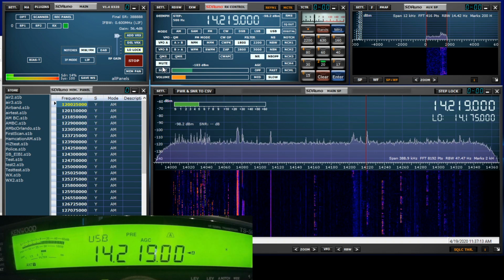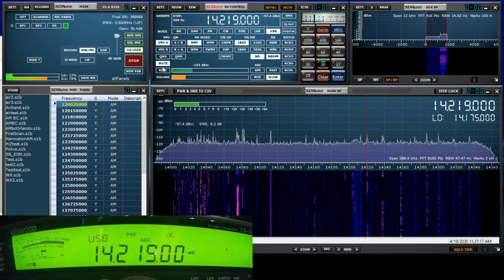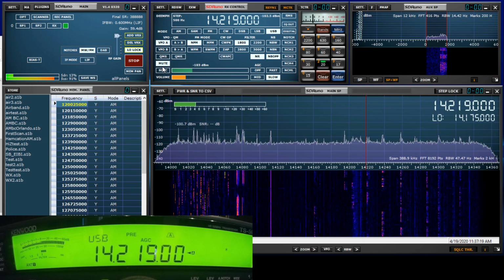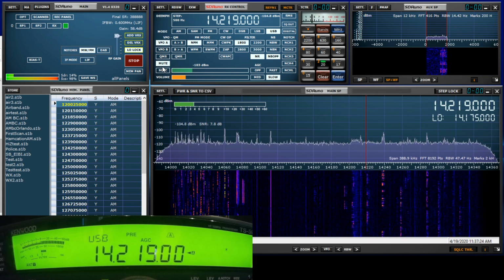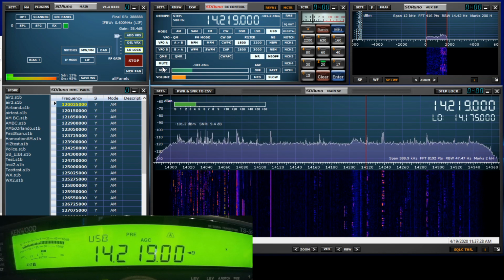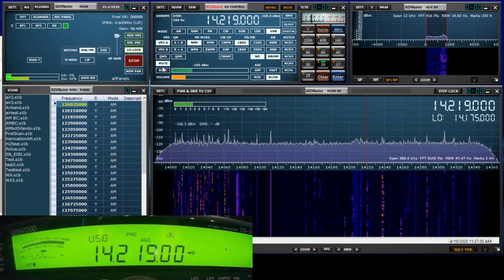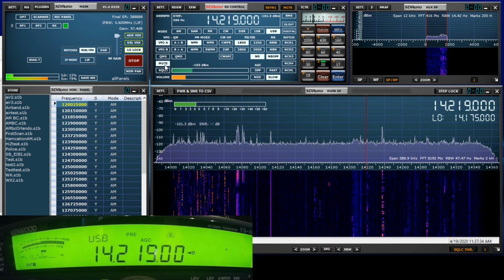The reason being, there is a delay due to signal processing from the signal that comes out of the rig through the RSP and through SDR Uno and so forth. So you will minimize that delay if you're actually wanting to talk to someone on the radio by using the receive side of the radio for listening, and then only using the audio through the PC when you're trying to find new signals. Okay.